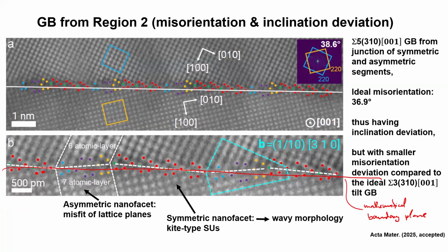This is also interesting because when you look with more and more high resolution at the grain boundaries in your material, you will see that there is always a tendency for faceting. It could be very small, so the facet length might be so small that you only see it with real high resolution methods with atomic resolution. But the tendency is there, because then this facet can be filled with one structural unit, and that saves energy. But then there must be another facet, and this is probably a different structural unit or an arrangement of different structural units, as shown here.